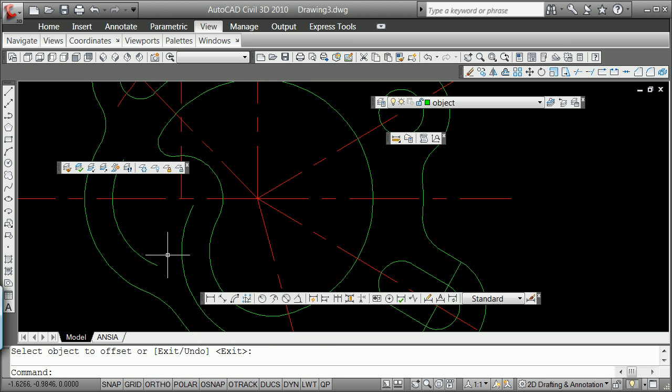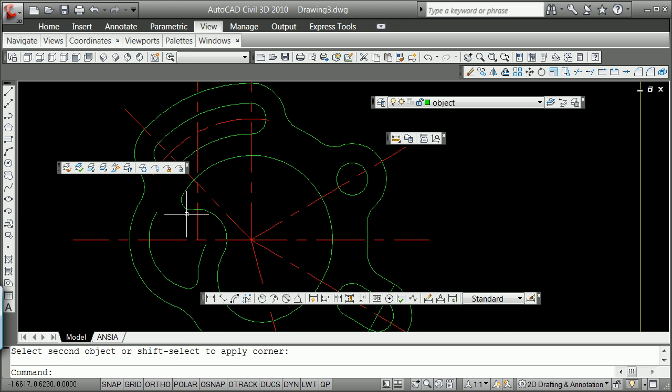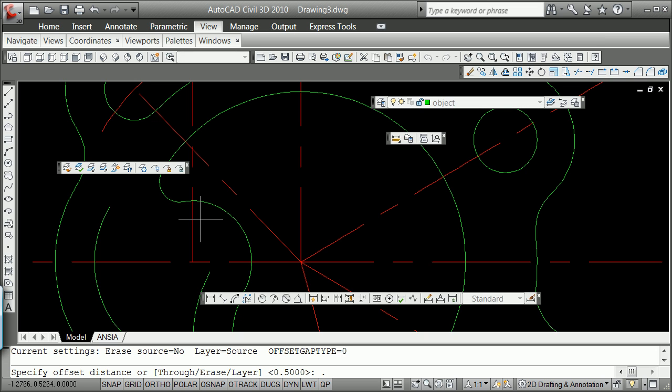Your assumption becomes eventually that there's going to be a fillet here of 0.25, fillet radius 0.25. We hope that this works. If not, you do a tangent radius. Now your last bit is to understand that as this thing comes around, this is also going to be offset 0.5, keeping the thickness on the gasket. Take that there, that comes around that way, and then this way is going to be offset 0.5 as well. And then finally fillet 0.25.